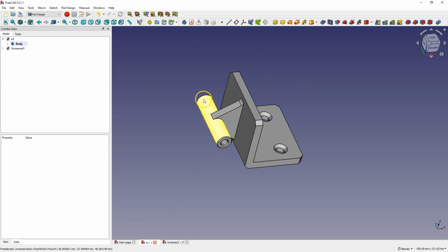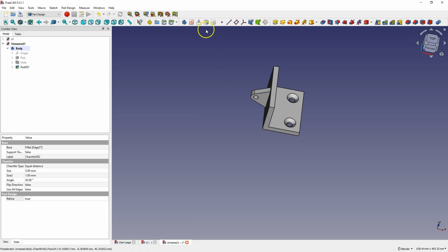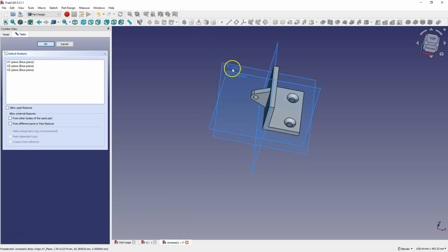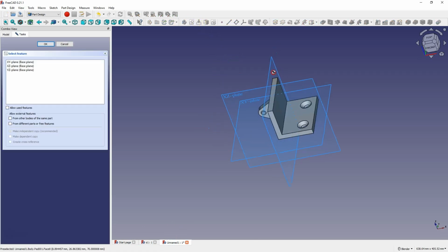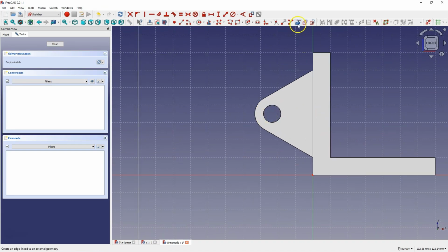And now create this part of the solid. That is, create a new sketch again. Select the XZ plane. And now use the reference geometry and click on this arc. Then click on the circle, and right-click to cancel this command. Switch to the section view and select Draw a Circle and draw one circle, the center of which will be at the center of this circle.